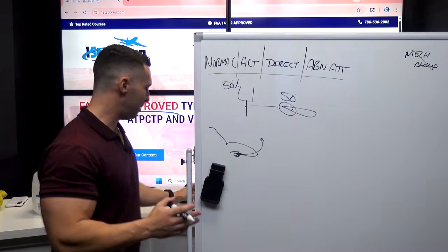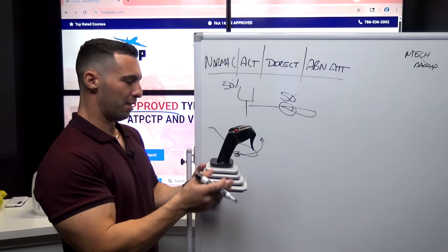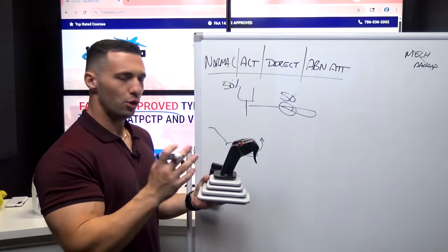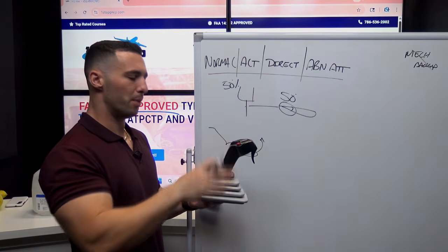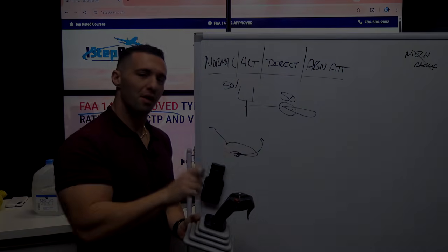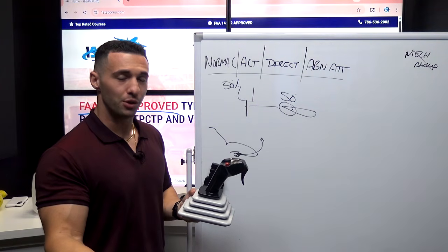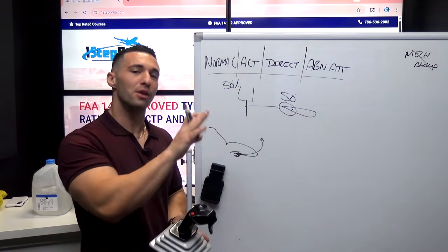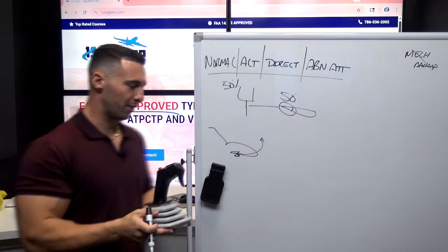And the reason it settles is because the flight control computers are looking at your side stick, and the side stick input is nothing. And so because I'm not commanding anything, the ELAC says you want no G change, meaning no positive, no negative G. I don't want any pitching moment, but aerodynamically the thrust is causing that nose up tendency. So then the ELAC says you don't want any G change, and it actually begins applying input for you to not have the nose come up, which would be the natural tendency of the jet to bring the nose up if we didn't actually have this G-load roll rate flight control characteristic.